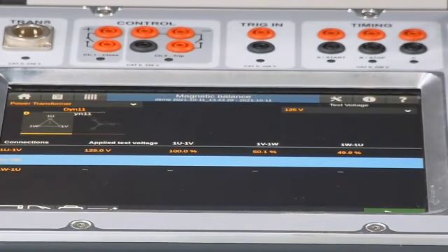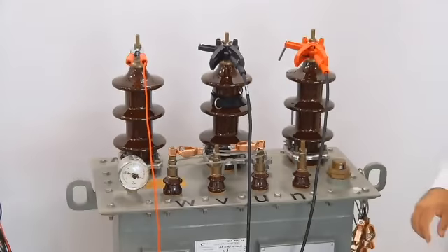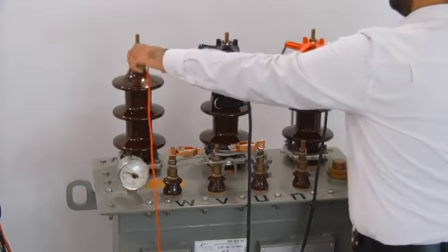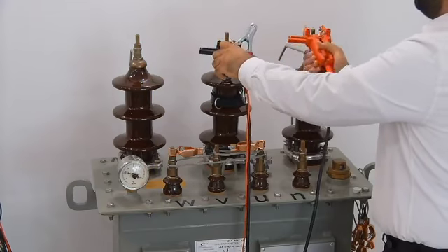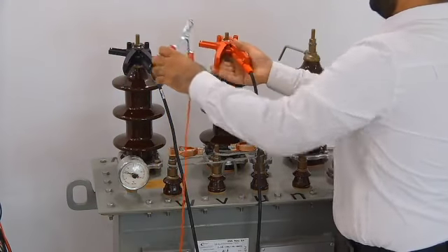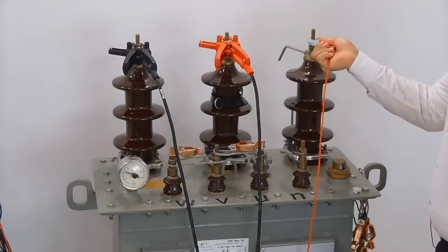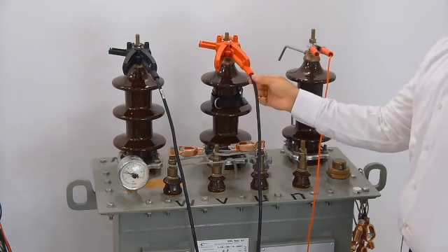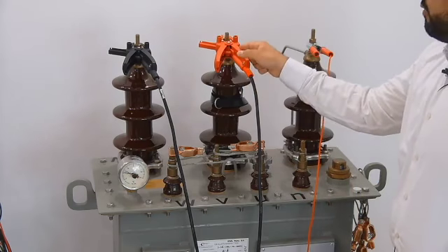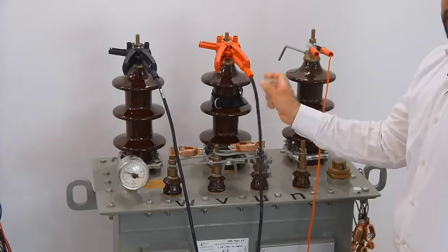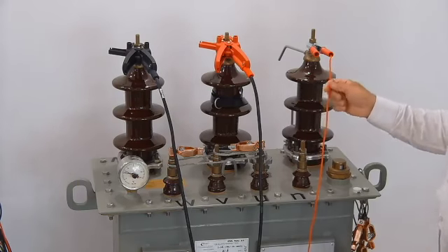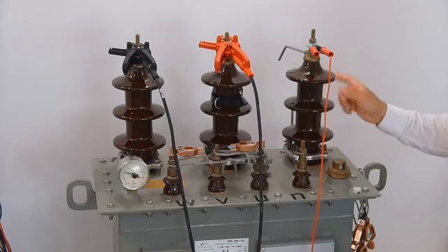I will now start switching the cables to make the next connection. I will start from the test setup. I will be doing a full shift. I will apply it from here, and I will measure across the three phases because this is Kelvin, which has two wires: one to put the voltage, and one to measure the voltage. Same thing here, but from this phase, I'm only measuring the voltage.